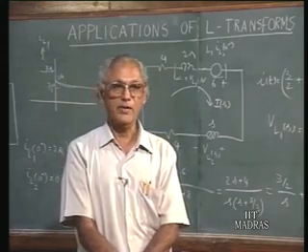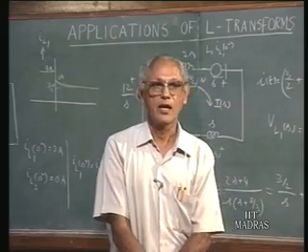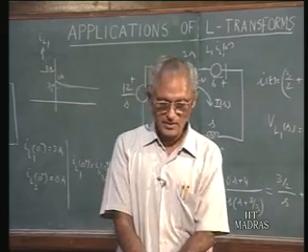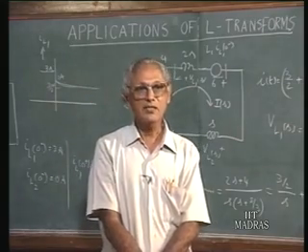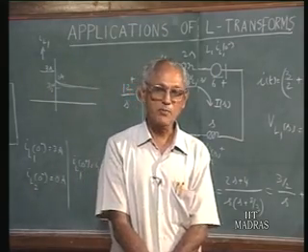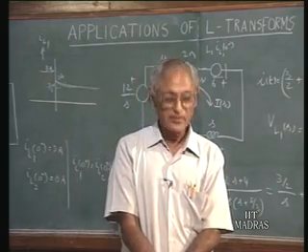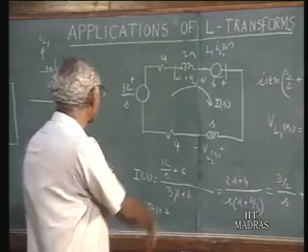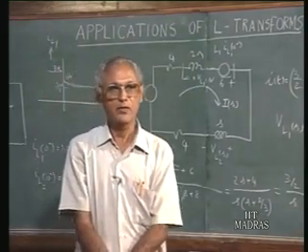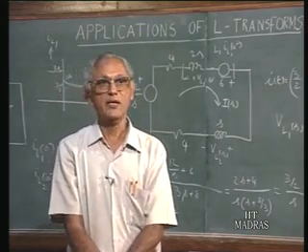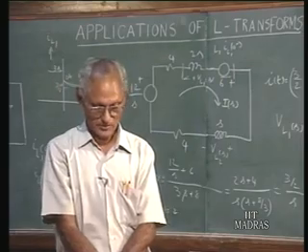And this becomes quite complicated because they are not evident, they are not given with the problem, and you have to calculate this. You have to find out the initial derivative, the second derivative, the third derivative through separate manipulations. All that is unnecessary as far as the Laplace transform technique is concerned. All the initial conditions pertinent to the reactive elements are used in the transform diagram, or equivalently in the differential equation. You substitute them and you get the solution. So separate evaluation of arbitrary constants is not necessary at all in the transform approach.